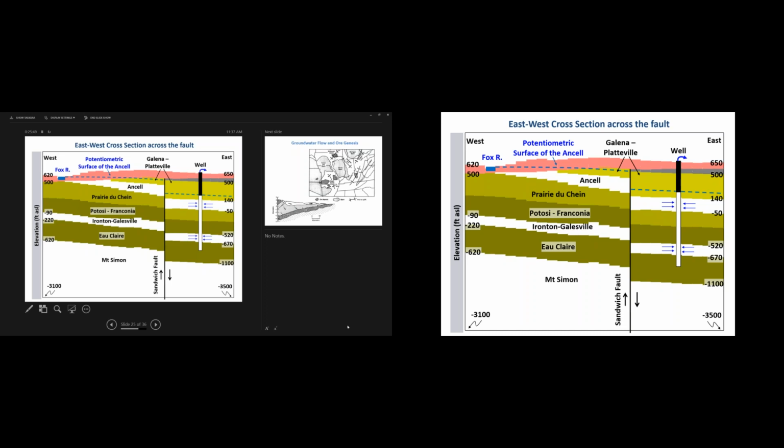So this is the geology that you put in. This is the geology we see on the screen. This is what MODFLOW sees. Right. And what it sees is these different layers, but because this is varying, our transmissivity here might be 5, it might be 100 here, and if this is where our cells are, it might go back to 5, then up to 20. So what it's going to see here is a 5, 100, a 5, and a 20. Yeah. Okay. So in each of these cells, it's calculating transmissivity and using that.